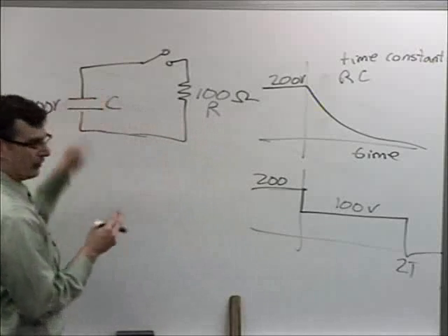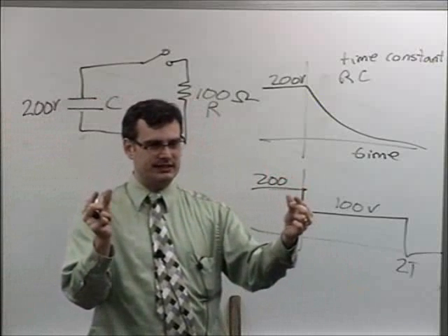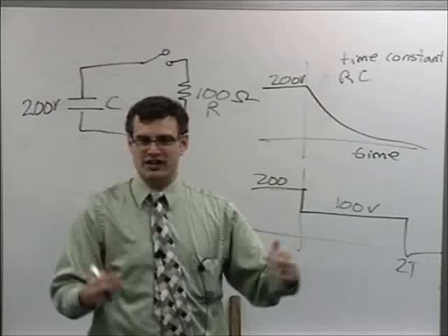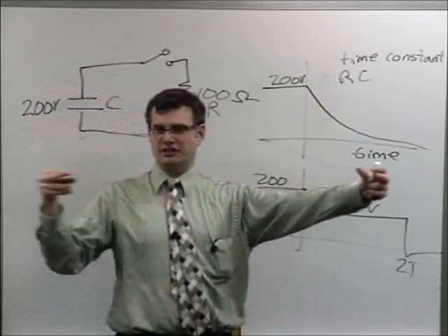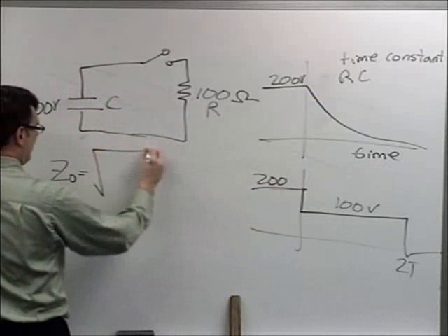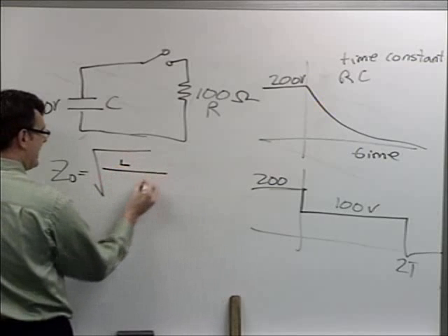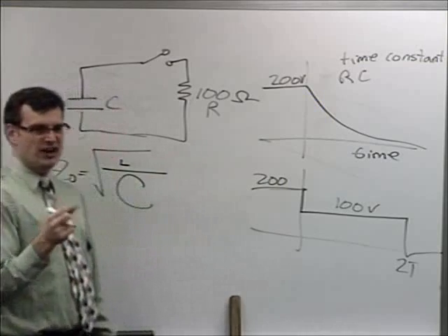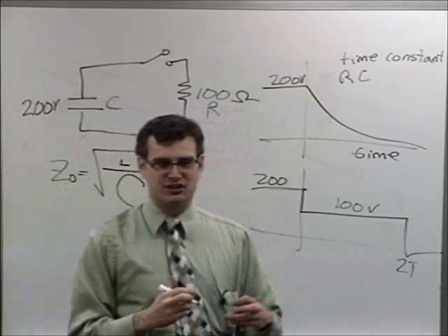This capacitor, if it's a good capacitor, is a nice thick plate with very little spacing to another nice thick plate. In other words, its intrinsic impedance for that long, skinny capacitor is probably a really, really small inductance and a gigantic per unit length capacitance, right? So the Z0 is actually pretty tiny, maybe milliohms or something. I don't know, it depends on the geometry.